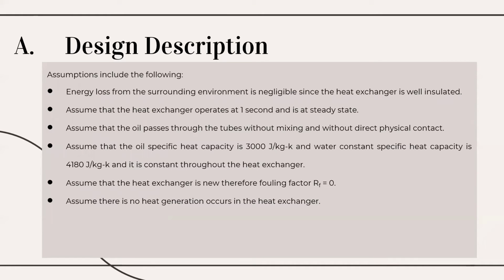Assumptions include the following. The energy loss from the surrounding environment is negligible since the heat exchanger is well insulated. Assume that the heat exchanger operates at steady state. Assume that the oil passes through the tubes without mixing and without direct physical contact.